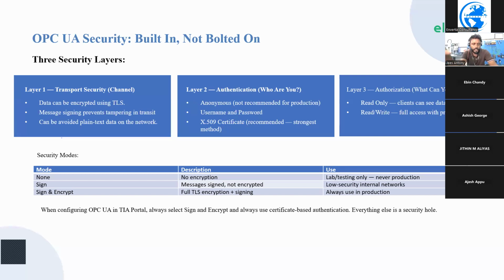Another type of authentication method in OPC is the username and password method. These are two different security principles implemented in OPC. You can use both username-based security and certificate-based security in the OPC network so that you have the most advanced security-based network in the plant. And with OPC this can be implemented very easily.